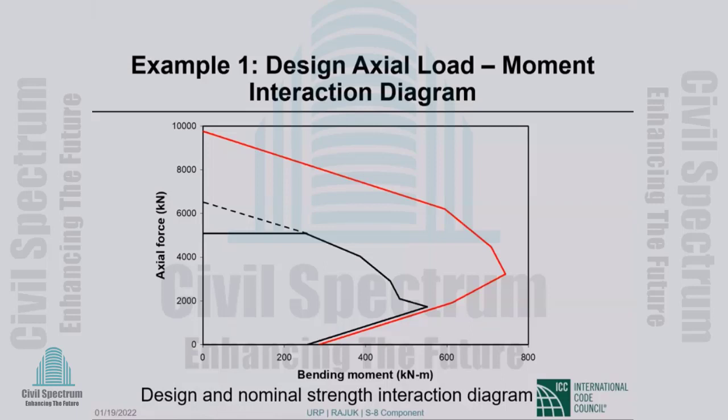You will typically not touch the column section because of other considerations, but you will reduce the reinforcement. These days, you can also play with the concrete strength if you like, and see if you can make the design less conservative. Anyway, so that is column design. You try something, you draw the load moment interaction diagram, you see where your demands fall.